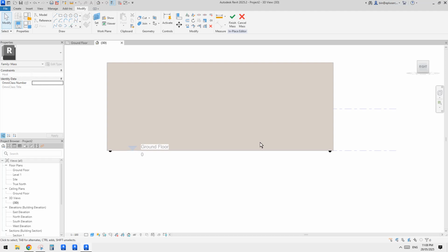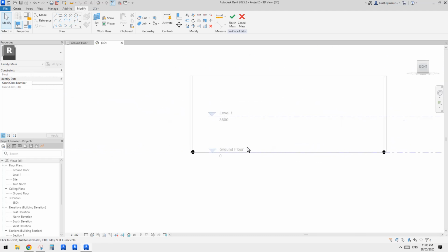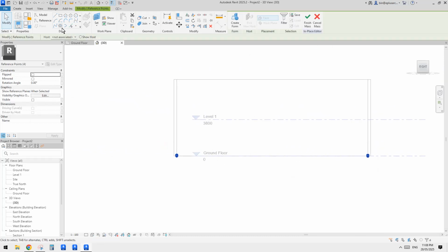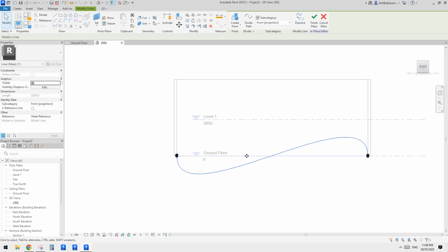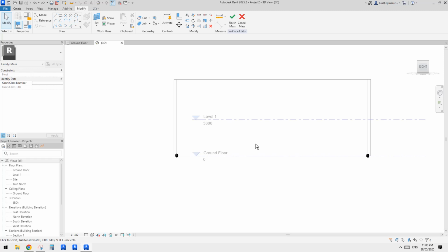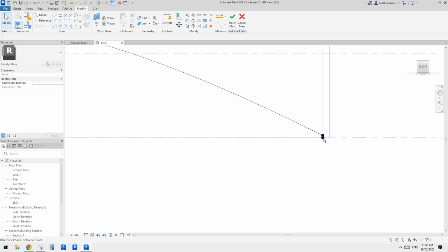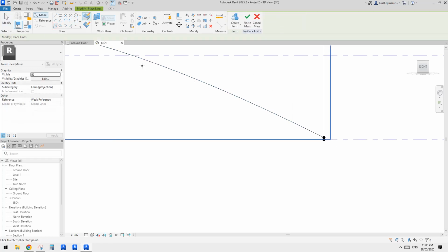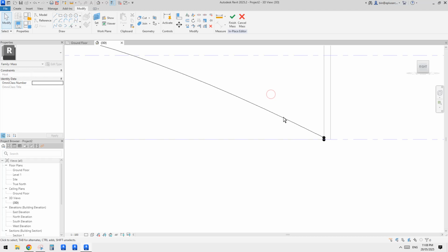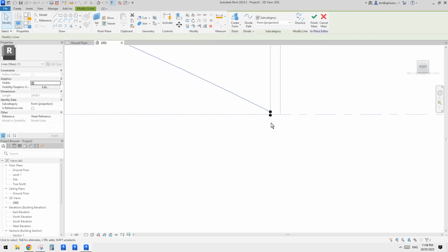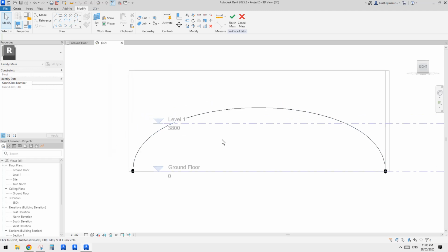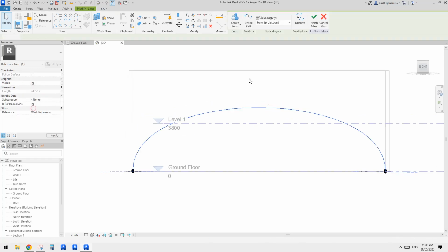Now I'll just type WF so we can see all the points. We can't create a spline by selecting all these 4, because we'll create this spline. So we are going to select these 2 together with the points on the top spline, and then Control select this point. Oh, sorry, try again. Control select, create. Now we have this one, and then let's make it reference line.